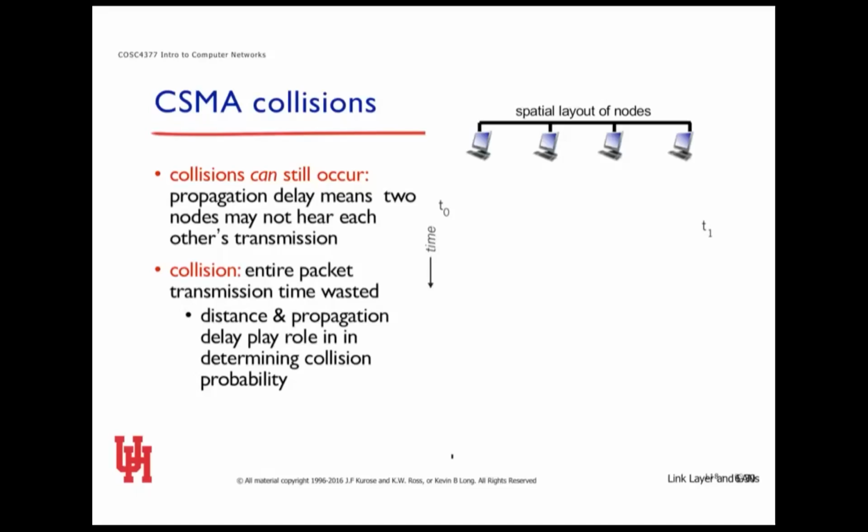So with this type of network, you're going to listen to see if the network is there, and if what you hear is just the carrier, which would be okay, it means it's idle, or if you hear something else. It doesn't matter why it's something else. If it's significantly different from the carrier, you're going to assume the channel is busy, maybe by another user on your network, you hope, maybe by some outside interference, if it's a wireless network or cable that's outside. Doesn't matter, you'll lay off. When it's available, when you sense that it's open, you will begin using the network.